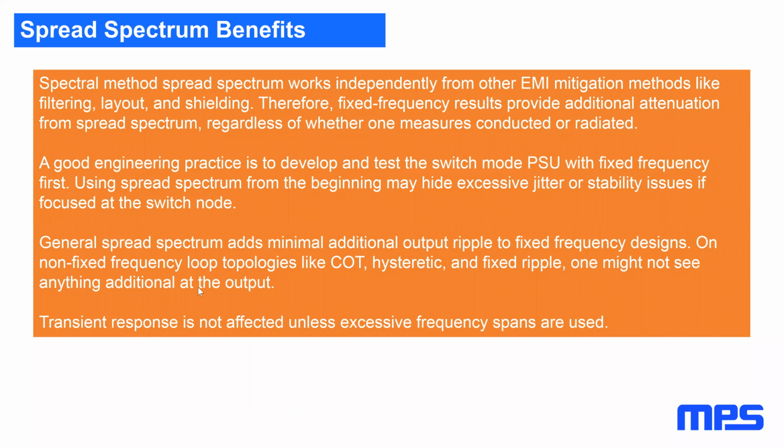The good thing about spread spectrum is that it works independent of all the other methods I told you today, so shielding and so on. With spread spectrum, you always add additional attenuation, and typically you will get a little bit of free spread spectrum on the high-end harmonics.